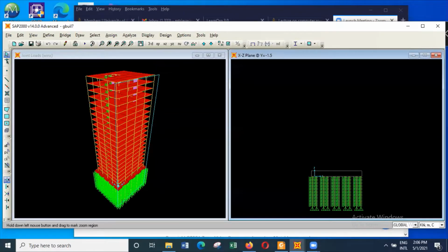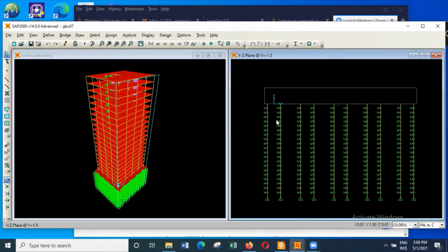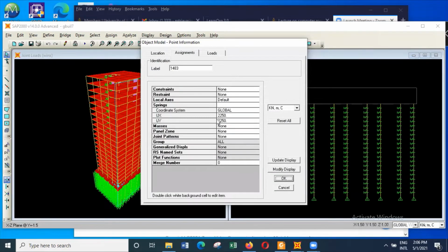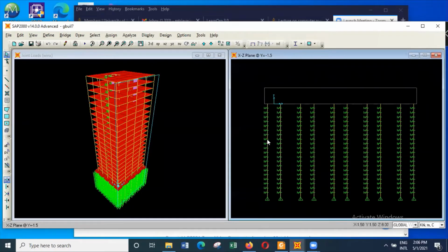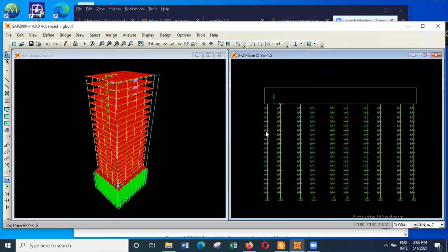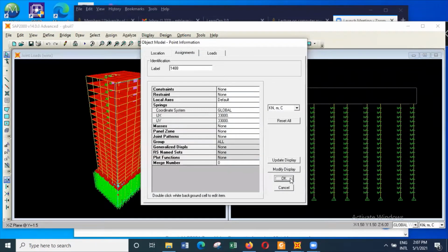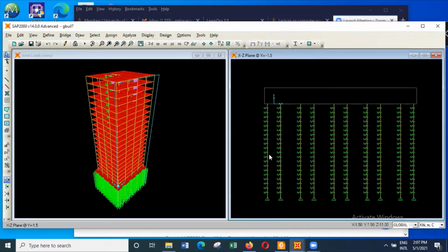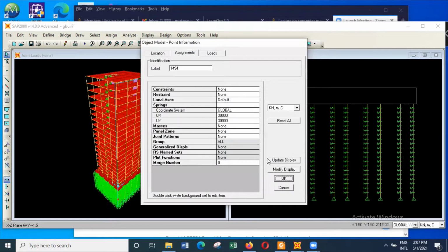And we also discussed in detail how we can assign these horizontal springs. For weak soil, we assign low values. And for medium soil, we went for higher values. But in this particular region, I think we have considered that it's a sandy soil. Whereas here we consider it as sandy soil in these areas. And then after that, we consider it as a laterite soil, where, because it's below the water table, we consider that the spring constant would remain the same.